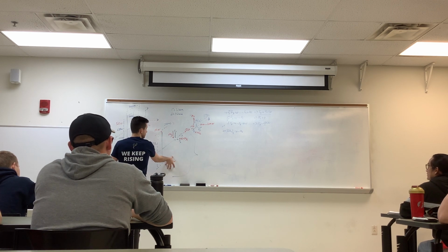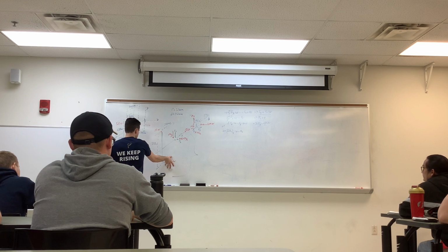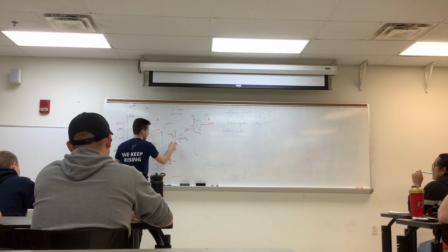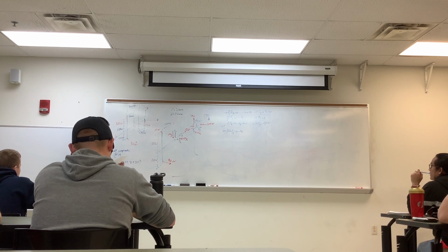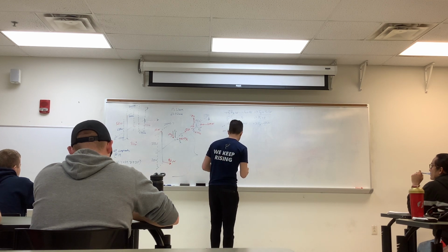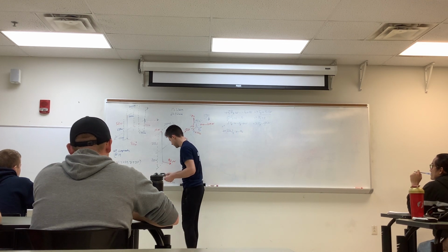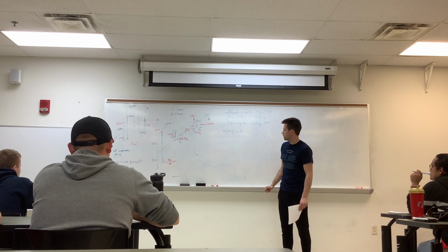This 90 kilonewton force is in that x plane, so we don't even need to worry about it. It wouldn't even cause any moment about point O anyways. So the only thing that causes moment about this x-axis is this 55 kilonewton force at a moment arm of, I'm going to convert this to meters, 0.225. Is it 55 kilonewton or newtons? Newton.